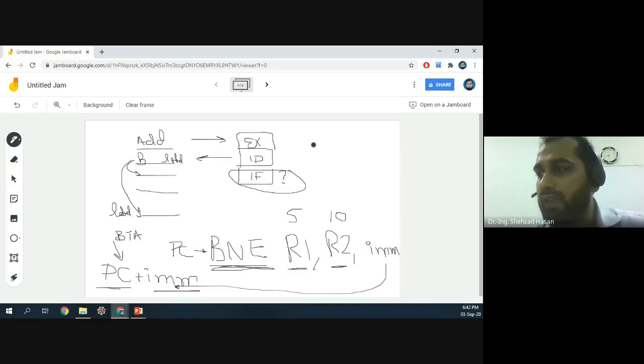All of these things can happen over here, but it's not normally happening over here. What we do is calculate this branch target address in the execution stage, and the condition also in the execution stage. In a normal branch, in the 5-stage pipeline that we have discussed, both the branch target address and the condition for the evaluation of branches are done in the execution stage.